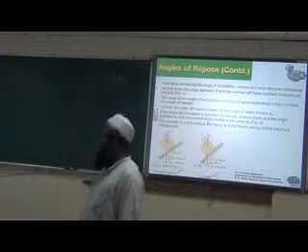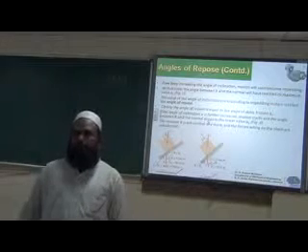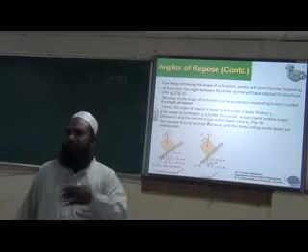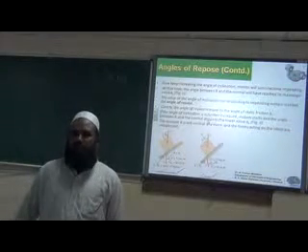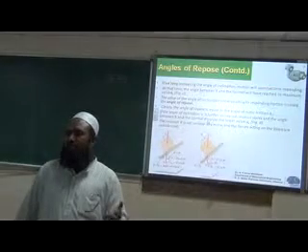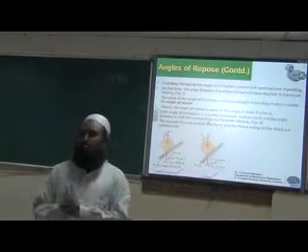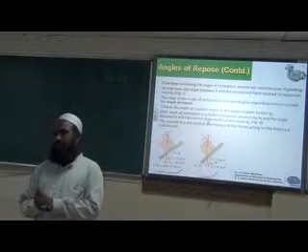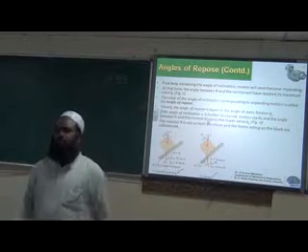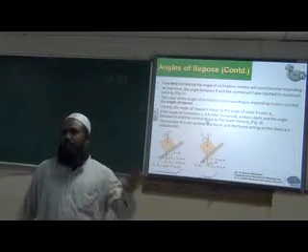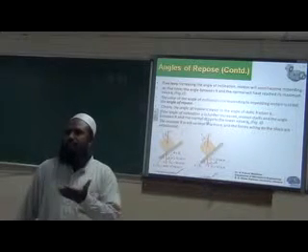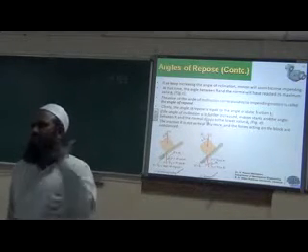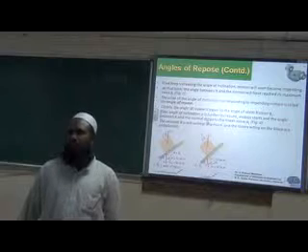So in friction, how will you classify friction? Static and dynamic is one classification. Static and kinetic. The other way, dry and wet friction. Okay, dry friction: friction between the two dry surfaces without any film of liquid between them. We call it as dry friction. Generally, our syllabus is confined to dry friction. Also, there is wet friction, where we have a thin film of lubrication. Okay. So under wet friction we have journal bearings, all those components we have to take.